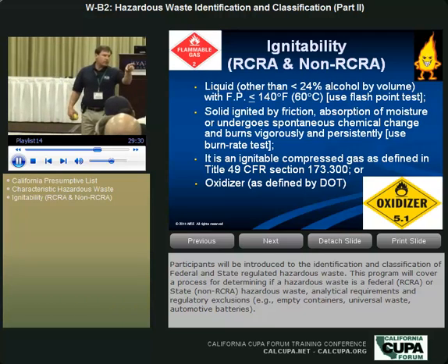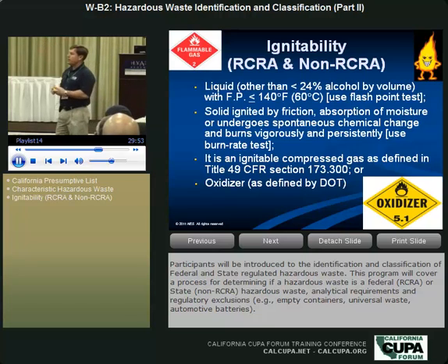Subpart CC describes instructions for DOT containers that have to be closed prior to transportation. So you're using a container for a facility. Subpart CC requirements for VOCs above 500 fugitive emissions apply to large quantity generators using DOT spec containers. Otherwise, they have to have a system to scrub and accept the VOCs prior to discharging to the outside ambient air. So we're twisted up in our underwear, and I haven't answered the question yet, right?